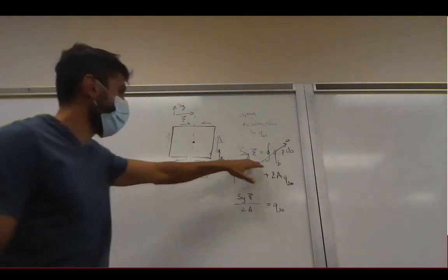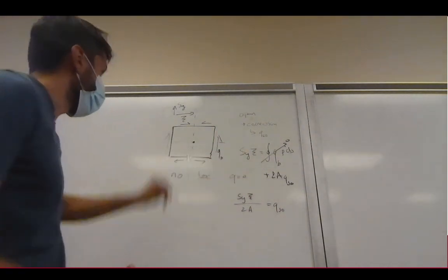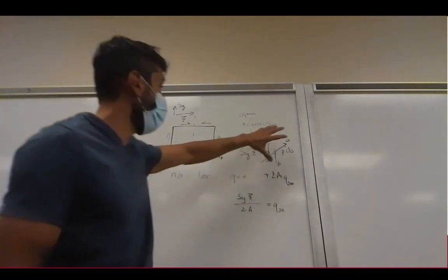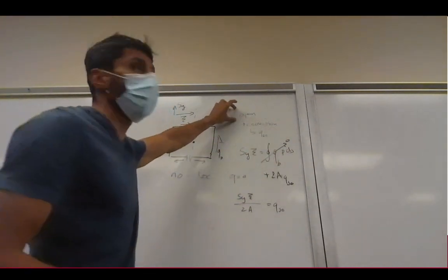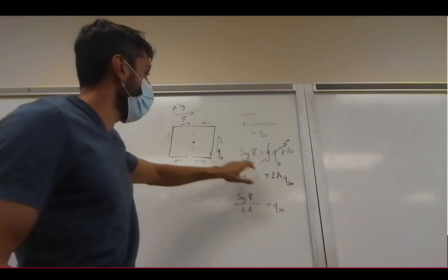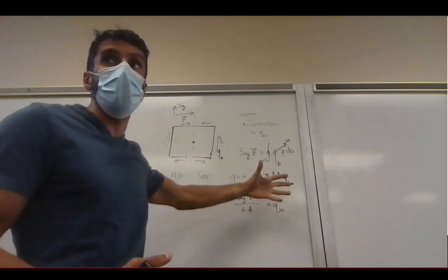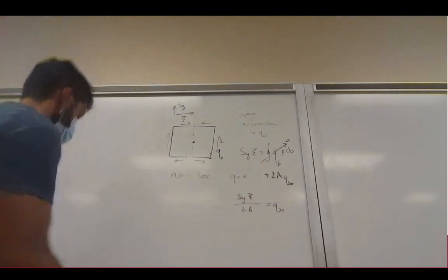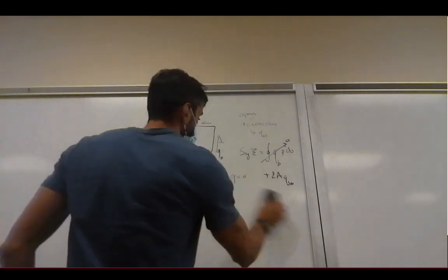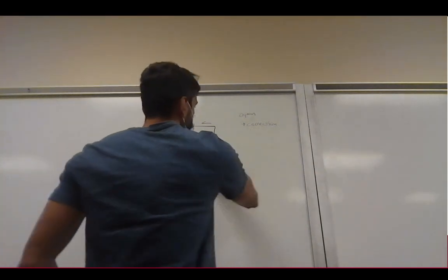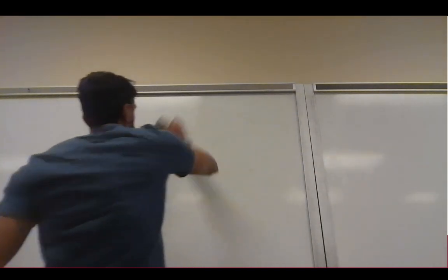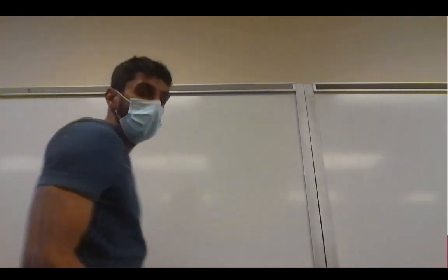In this case they cancel out, just because of how I drew it. But normally all this is known because you solve the open shear flow problem, and you have one equation with one unknown, so you can solve this. And then you add the correction shear flow to the open shear flows, and that's your final solution.